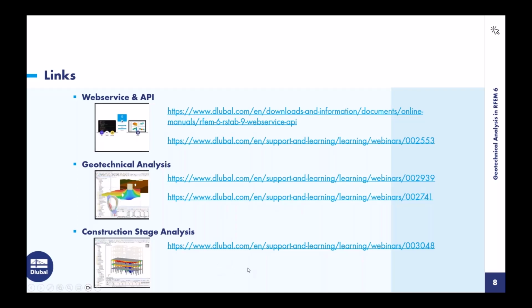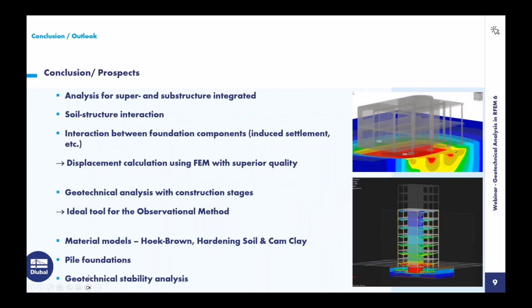As for the higher soil material models, it's quite common to use the construction stage analysis, because you can then more in detail consider the stages of the construction and the loading, and therefore the correct stiffnesses, as we remember, the correct stress states and the correct stiffnesses in the soil. So it's connected to our topic. That's enough for this one.